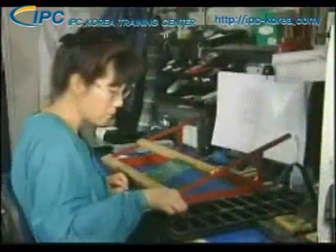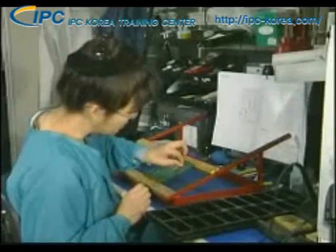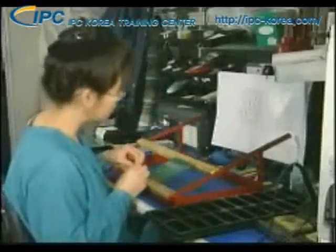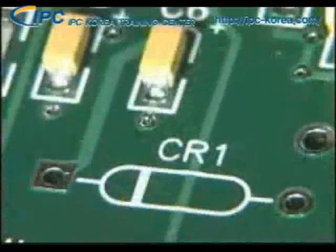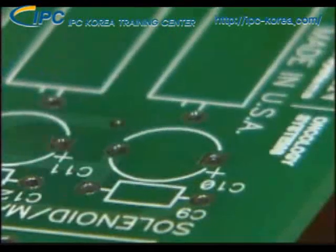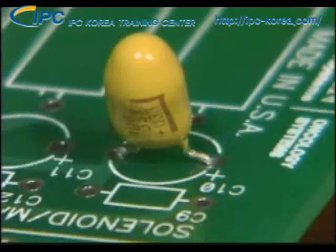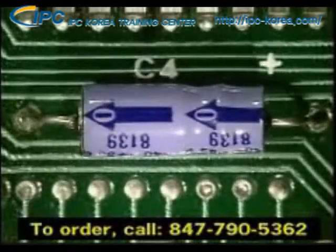Now that you see how the bill of materials and assembly drawing are used to identify the proper components and their locations on the circuit board, let's examine another important topic in component identification: the direction or orientation in which the component needs to be installed. Some components have a positive and negative connection to the circuit board, and the leads must be inserted into the circuit board in the correct position. This means the positive and negative leads must be inserted into the positive and negative holes identified on the circuit board and assembly drawing. Components with this positive and negative connection have what is called polarity.